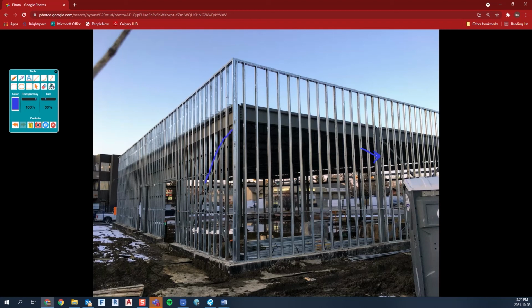What the other part that's really interesting about this as well, so these steel frame buildings generally have bracings. I can see some bracing right there. There's some steel bracing in there. So you remember in the previous pictures I showed that bracing, the studs were framed around the bracing. There's another brace over there. Now the studs are on the outside of all that structure. So what that means is on the inside, you see the bracing. So you'd have to fur around it if you didn't want to see that bracing on the inside, which again, the bracing's taking up an entire grid bay basically there. So you'd have to fur out a fair bit of wall and you end up with two walls essentially. So anyways, I was shocked when I saw this. I didn't see that very often.